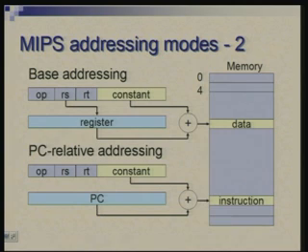Okay, we have load store instructions which make reference to memory, but your arithmetic instructions or logical instructions always assume operands to be in registers or constants. Okay. This mode is not available for instructions like add or and or.